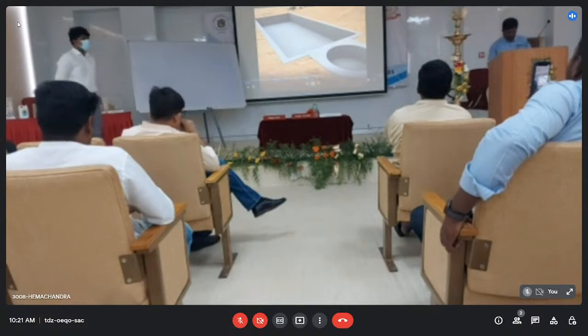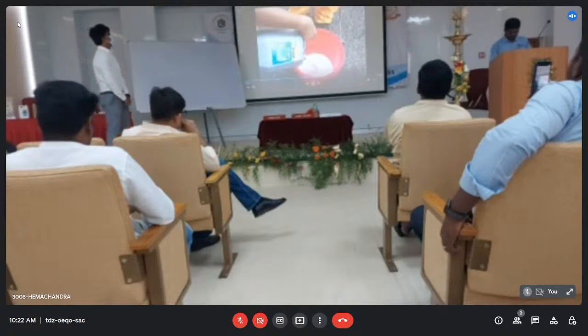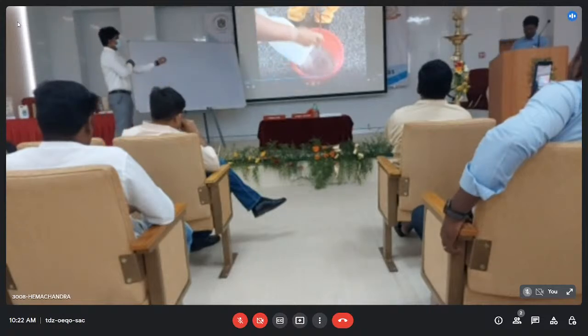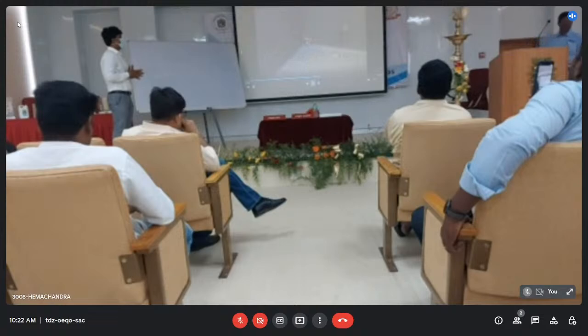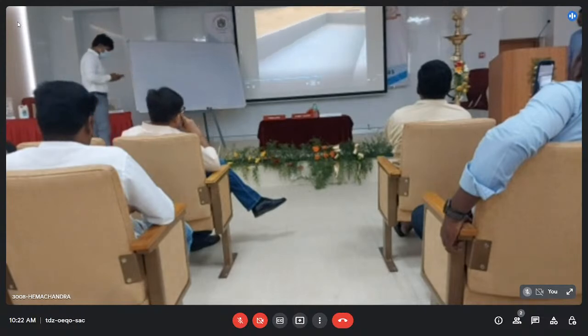Allow this coat to dry for 4 to 6 hours. Now, prepare another batch of Dr. Fixit Fast Flex as before. Apply a second coat of Fast Flex. The direction of this coat must be 90 degrees to the direction of the first coat. Again, allow this coat to dry for 4 to 6 hours.